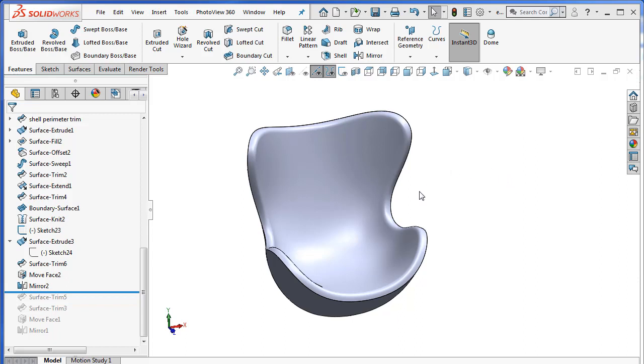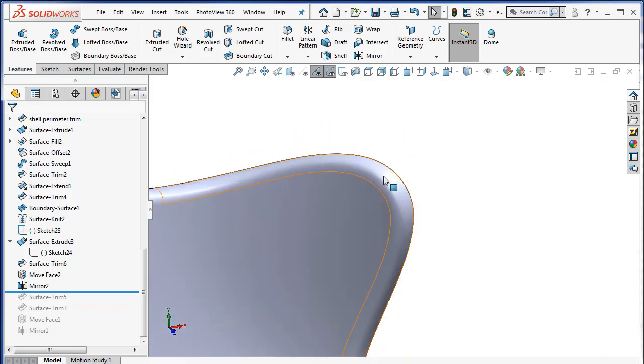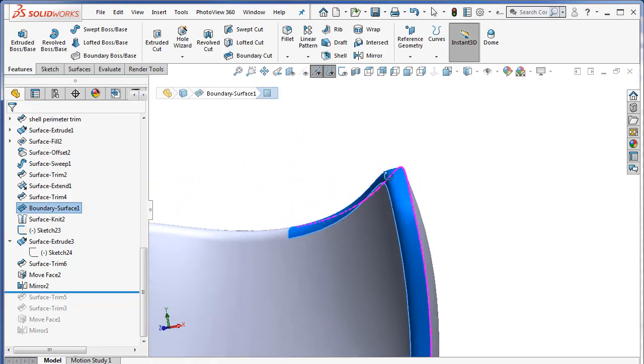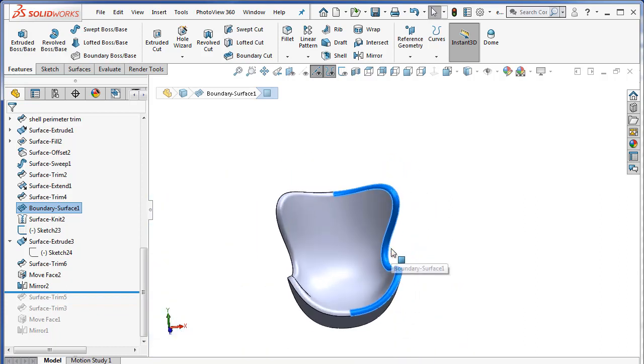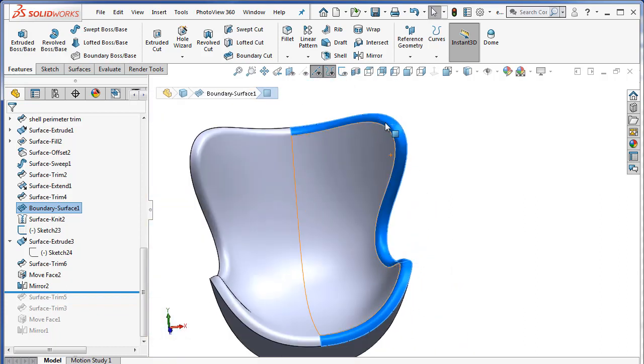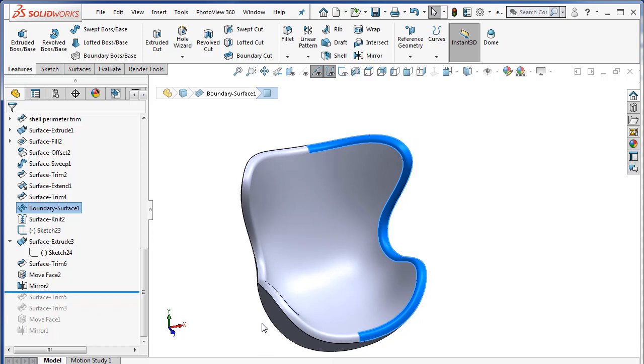Okay, there's one other issue that I want to talk about. Again, this is on both the womb and the egg chair. And that's when you're adding this transitional surface to give the puffy cushion look. You probably want to have some intermediate cross-sectional sketches like here, here, and here. And you have to be careful how you draw those.